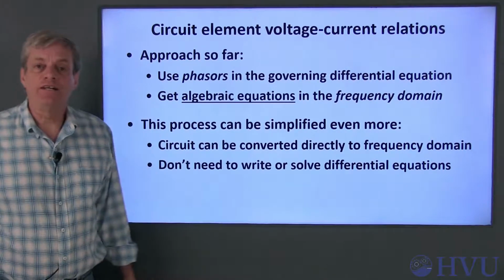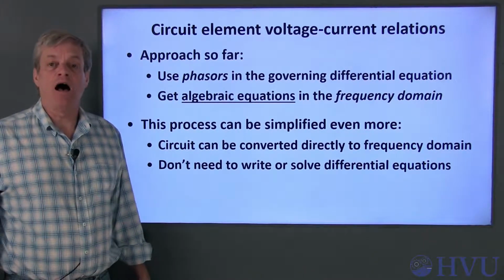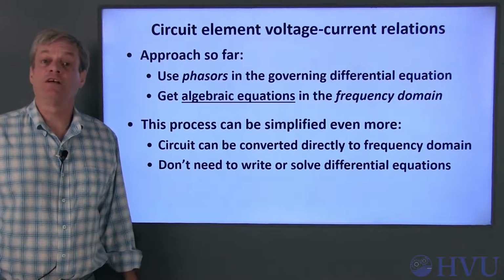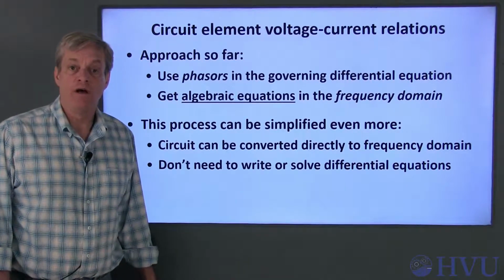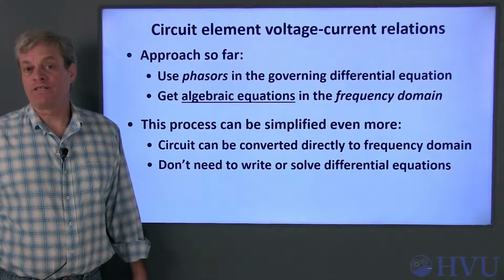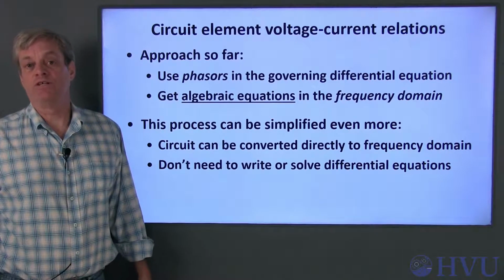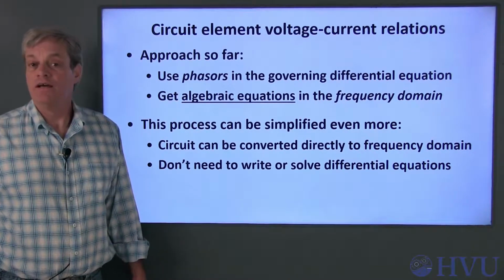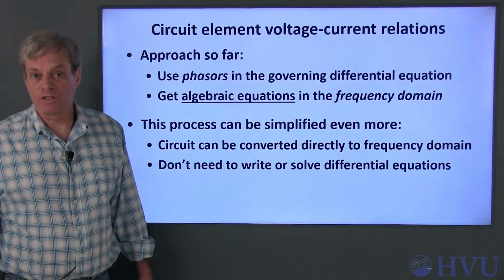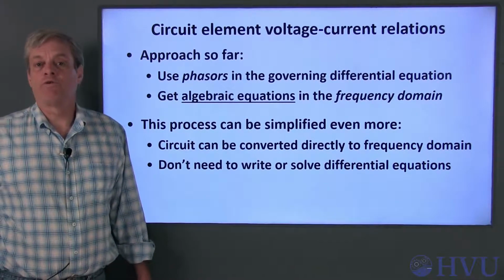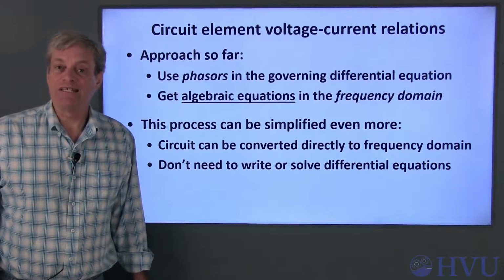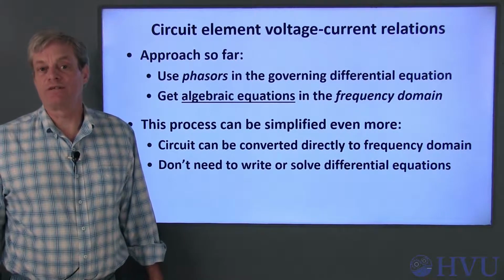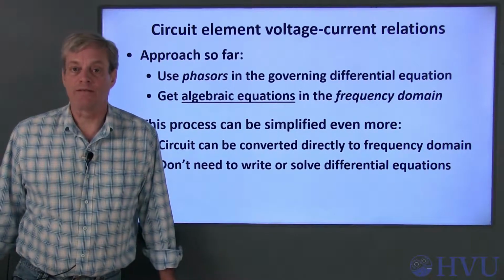There's a huge advantage to frequency domain analysis beyond just writing a differential equation and converting it to an algebraic equation. We can actually convert the circuit schematic itself to the frequency domain and write the governing algebraic equations directly from the circuit, just as we did with purely resistive circuits. This eliminates the need for writing and solving differential equations entirely if we just need the circuit's steady-state sinusoidal response.